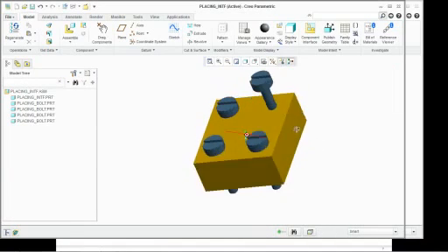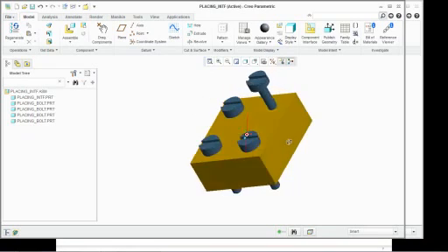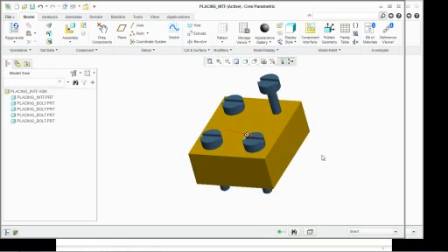But that saves me a lot of time in placing large numbers of components. It's one of the more time-saving things that I've picked up over the years using Pro E. Because typically bolts are always placed using a bore constraint and a surface constraint. Again, I wanted to squeeze those in at the last bit there because interfaces are extremely valuable with large assemblies.